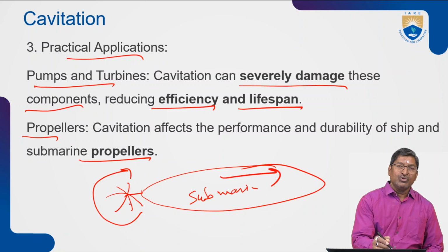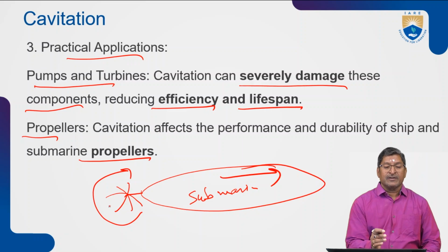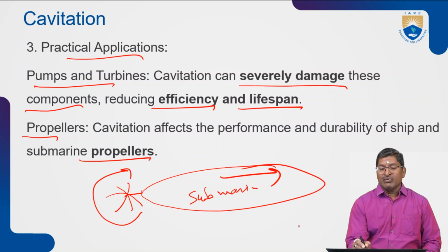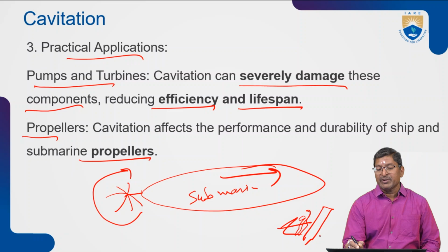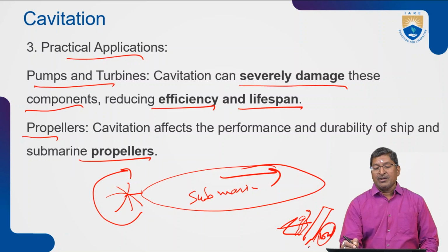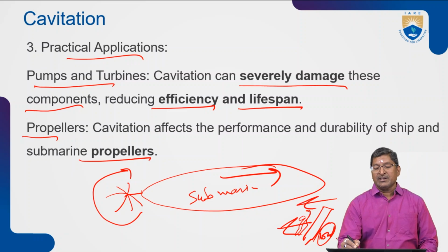While moving, at one side of this propeller very low pressure will be formed, because as the water is flowing and being pushed, high pressure will be there for the liquid on one side and low pressure at the same time on the other. Where the liquid is pumped in this direction, bubbles will form, that means cavitation will occur.